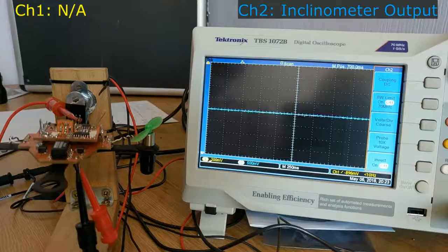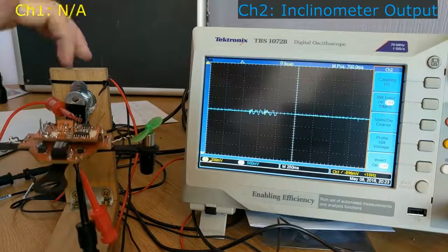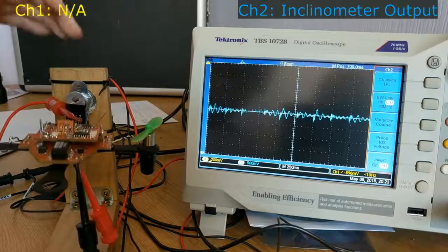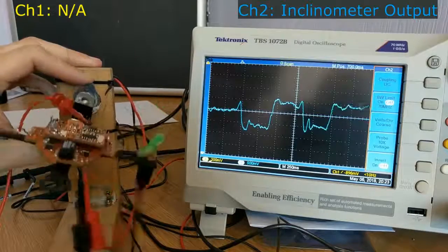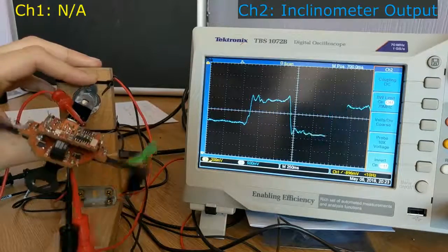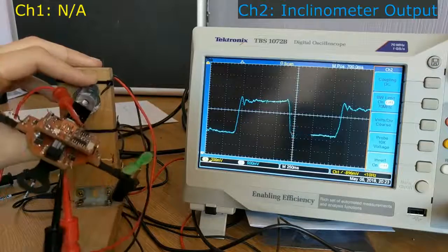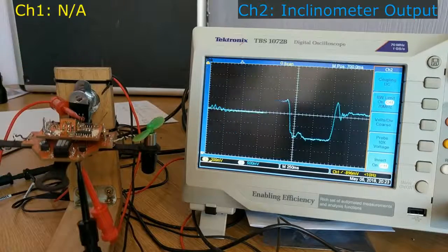This is the inertial measurement unit. It is used to measure the roll angle of the quadcopter. This is done using an accelerometer, or in my case an inclinometer. These devices are susceptible to vertical and horizontal vibrations and overshoot. That's a vertical vibration showing noise, and overshoot when measuring a fast moving angle.